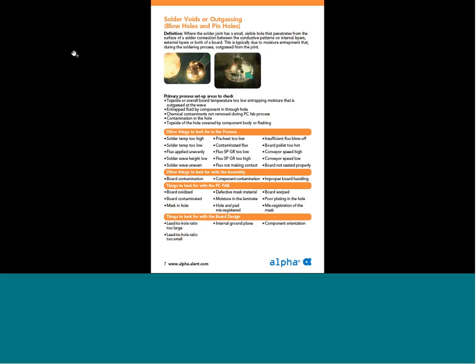How about your flux application? Are you sure you're getting flux on the entirety of the board? If you have a component in the shadow of a surface mount part and the flux doesn't get it right, you can see the pinholes, blowholes, non-wetting, de-wetting. Okay.